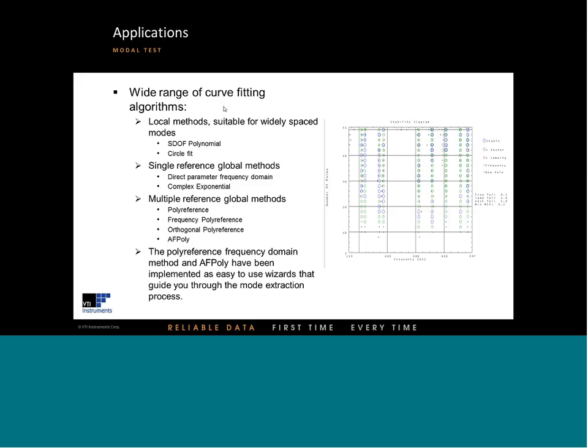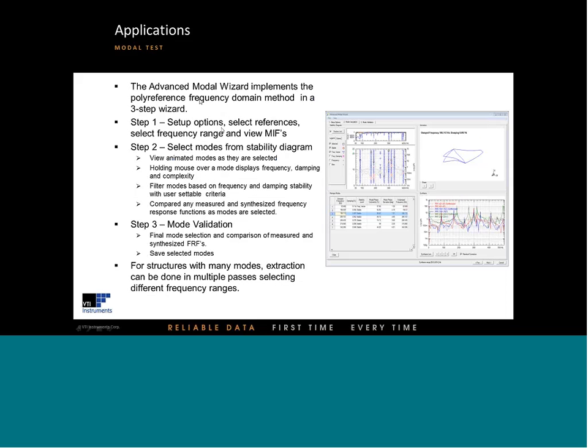The polyreference frequency domain method and AF poly have been implemented as easy-to-use wizards that guide you through the mode extraction process. And this is the example of the polyreference frequency domain. It's called the Advanced Modal Wizard, and makes modal analysis a three-step process.